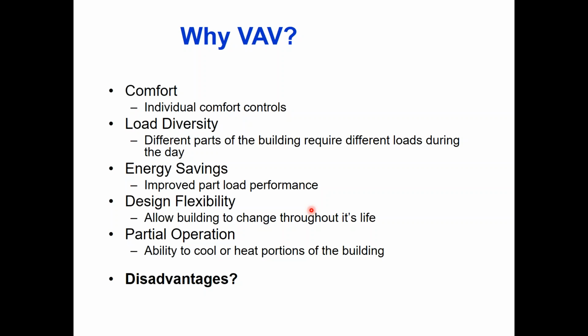There's going to be an energy saving benefit. Part of that's coming from the compression side of the equation, being able to stage things down. But honestly, the big energy savings on VAV, in fact almost all of the energy savings, comes from the fan system and being able to throttle that fan back. We'll talk about that in detail, and how we control that fan and where the energy savings comes from specifically. But the fan energy savings is going to be pretty impressive on a VAV system, and that makes it an attractive system for a lot of buildings.